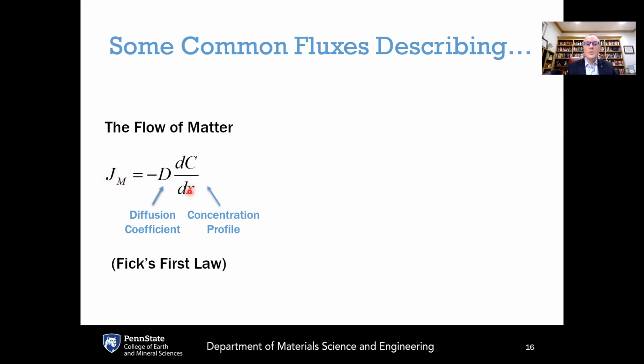Two things. One is the thermodynamic driving force, which in Fick's first law is a concentration profile of the material. If this concentration profile goes to zero, then there is no driving force for diffusion of matter to occur, according to this law. If there is a non-zero concentration profile, then there will be a flux of matter that acts to eliminate that concentration profile.